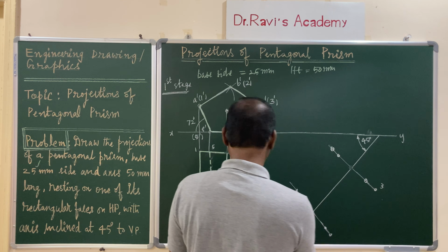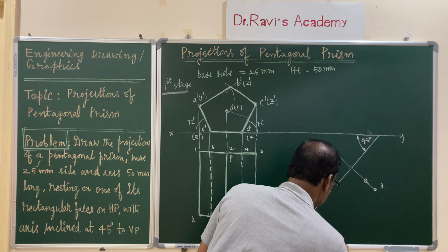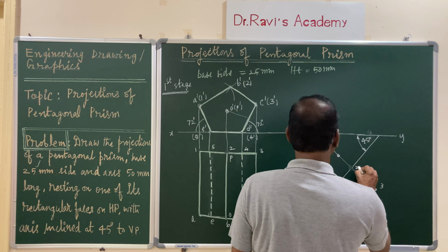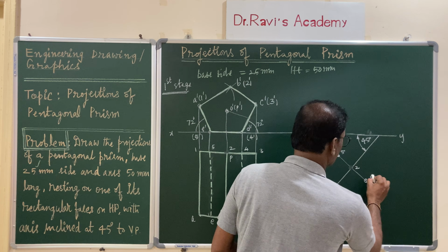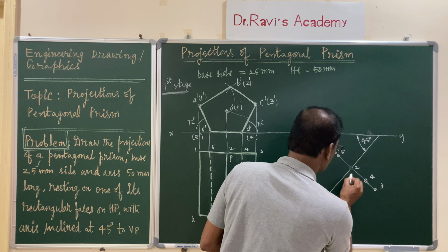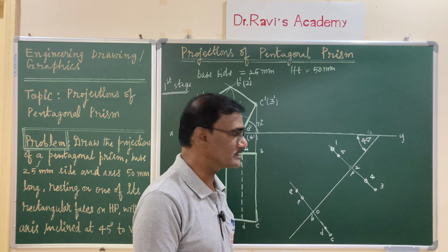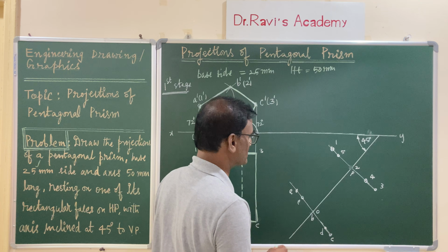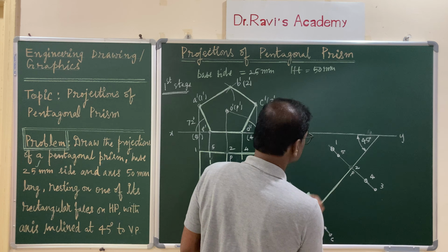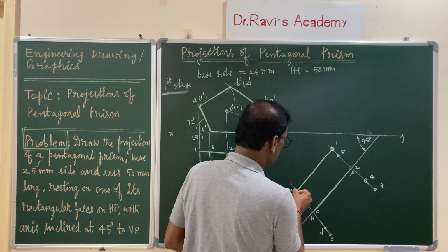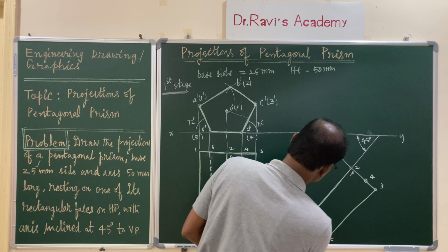So mark all this. It is B, and this is D, and finally this is C. Here this is 2, this is 5, 1, 4 and 3. Of course, this is O, P. So you have located all the points, corners of the solid, and join all this with HB pencil. So here this is one edge which coincides with the axis, continuous line, and this is again continuous line, continuous line, of course continuous line.